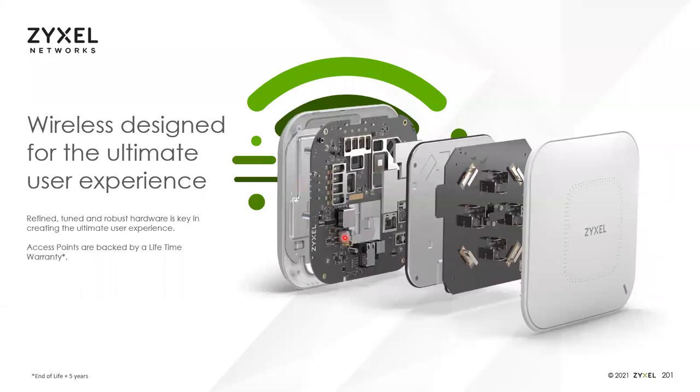The next thing you will notice is we have a lot more shielding on our PCBA versus most of our competition. In addition to just board level EMI, we're also providing shielding to neighboring 4G and 5G frequencies, which may cause interference on your 2.4 or 5 gigahertz radios. So we've added extra shielding to help keep that out.